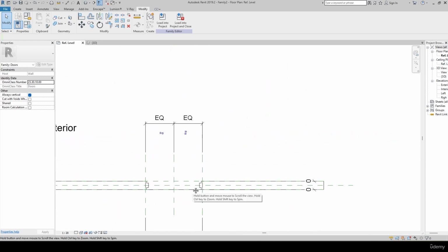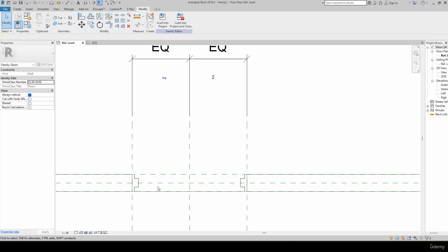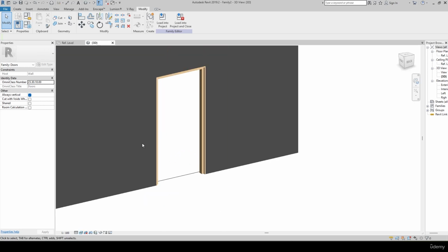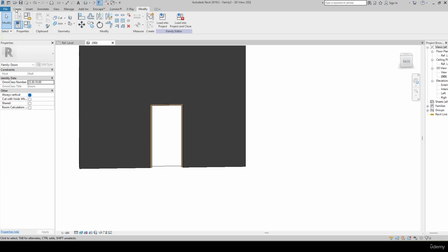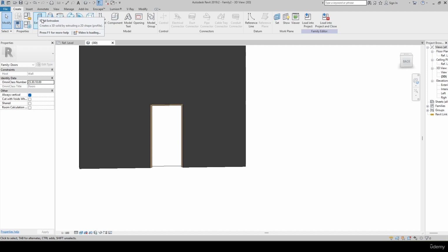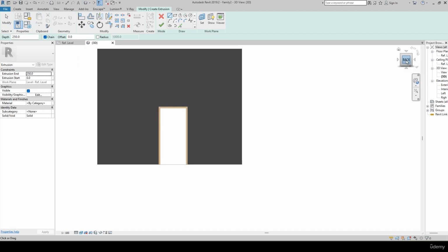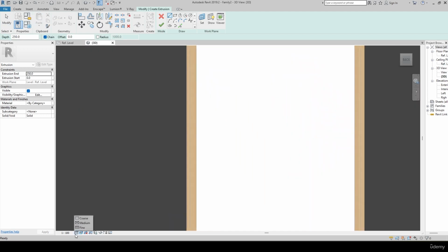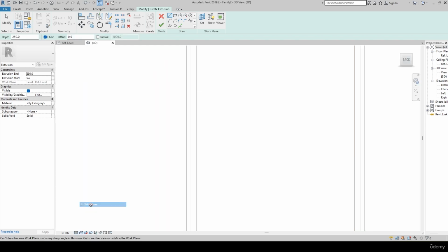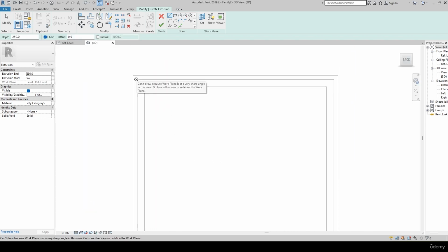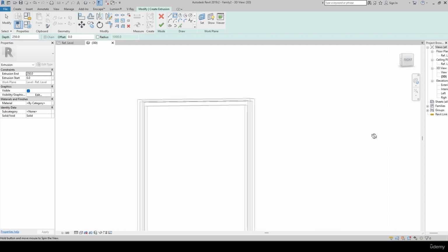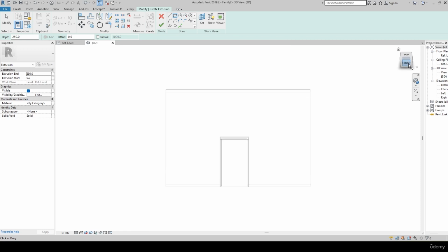Now I want to add the shutter for this. Okay, so in order to add the shutter, once again I'll go to the 3D view. I'll go to the option called create. Now I'll use the tool called the extrusion. Okay, so in order to do this solid extrusion I'll click on this. I'll go to the back. I'll enable the fine view. I'll enable the wireframe. Now I just select the form. Once again I want to create this in the front direction.